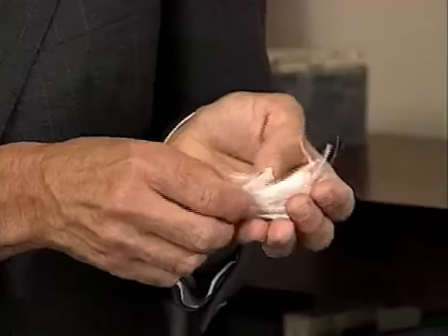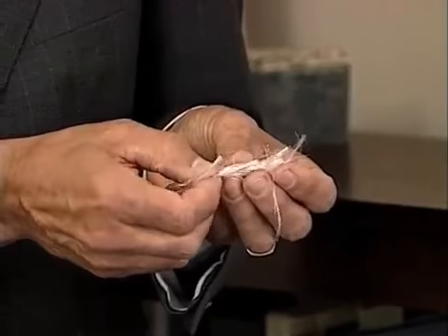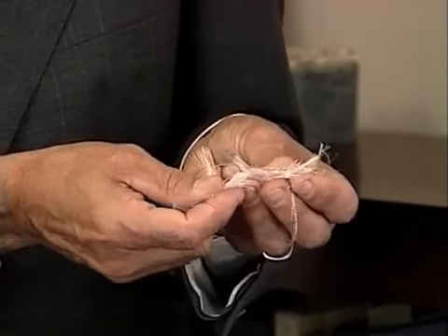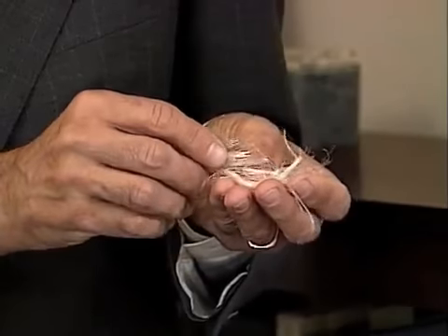Polypropylene and nylon fibers have a beneficial effect to concrete in minimizing plastic shrinkage cracks, not for drying shrinkage cracks. These fibers are added to the transit mix truck, and the mixing action distributes the fibers. They're added at a rate of about 1 pound per cubic yard.